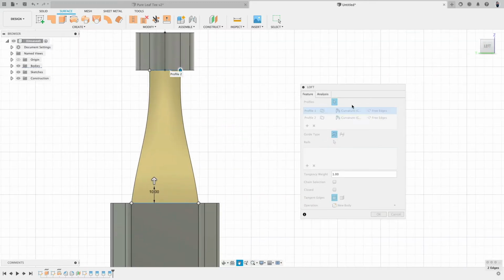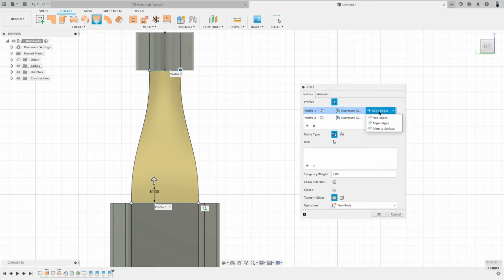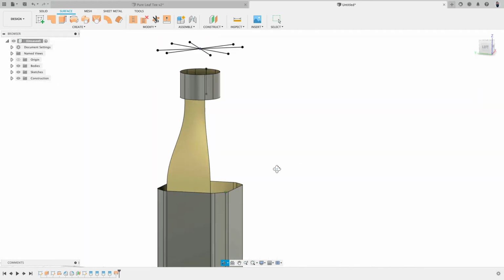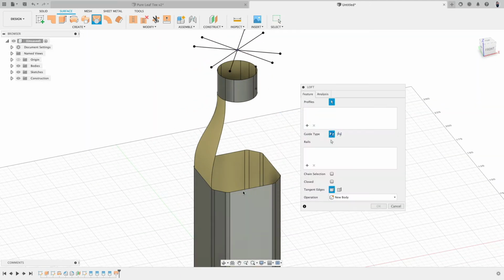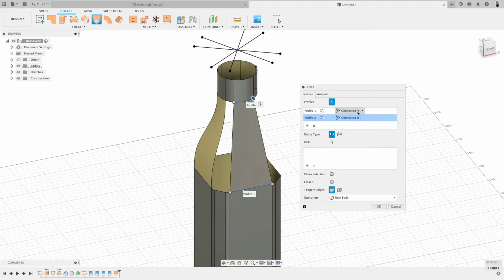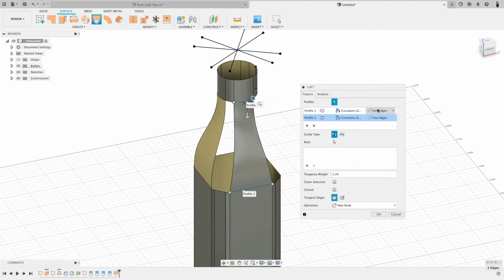So that is why on the right side we have this aligned surface. You pay attention to how this changes. And there you can see this continues and then blends. Same here. Very good. Okay, right click, repeat, click, click, G2, G2, align, align.